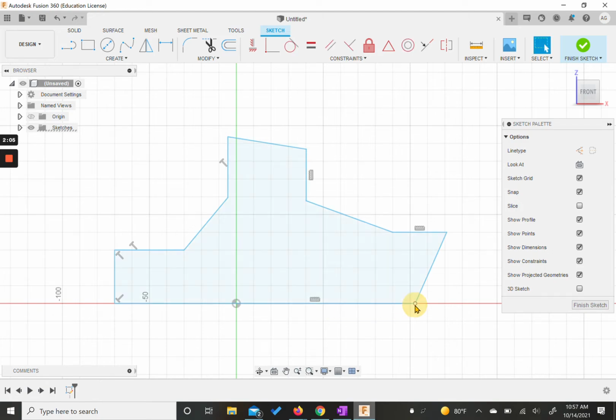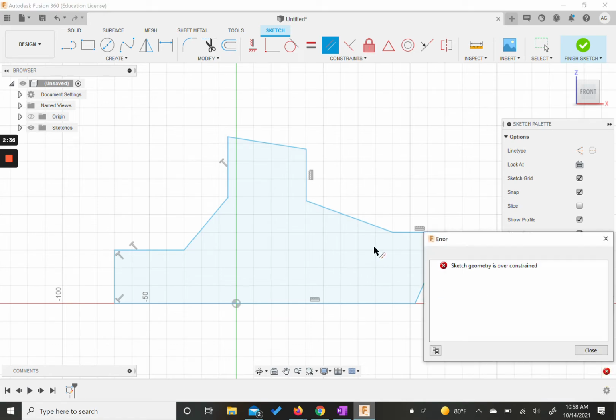With this shape, there's a couple different things that we're going to need. We want to make sure that these two lines are parallel. So we're going to come into our constraints, and we have a lot of them right here. Sorry about the bells. Didn't think about those going off. We'll probably have one more happening. But we have a parallel constraint that we want to add between these two. They're already parallel, so it's going to try and tell you that you have an issue. This depends on how you place them originally. Since we did vertically, we don't need our parallel constraint here.